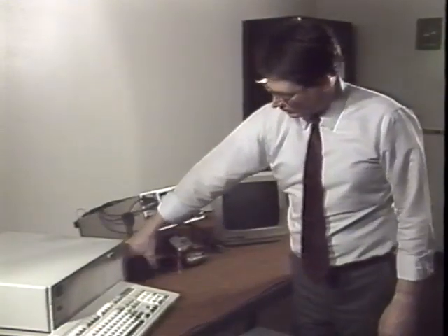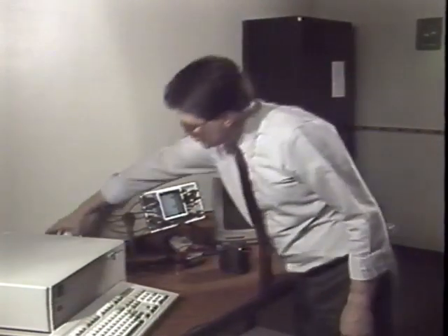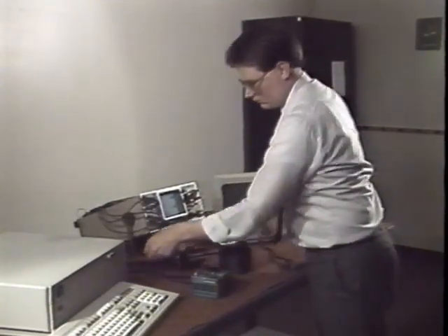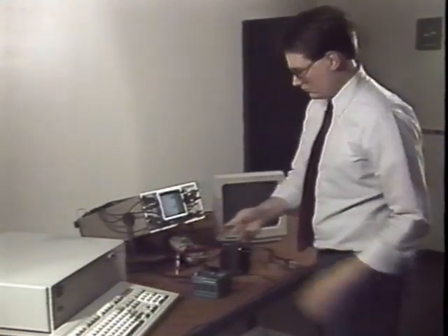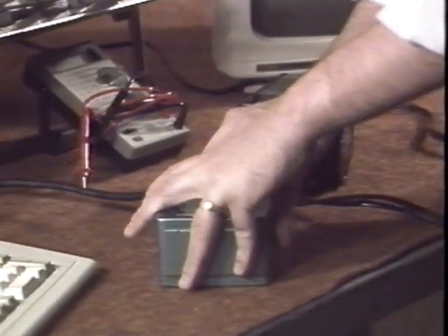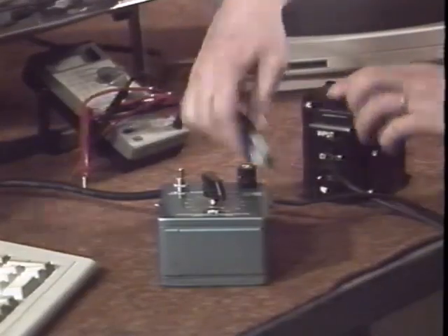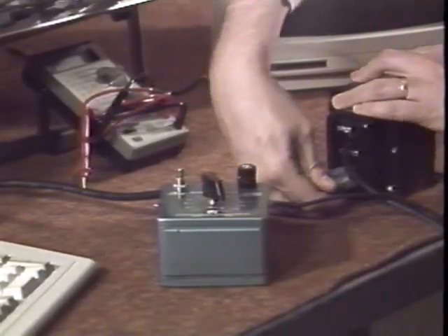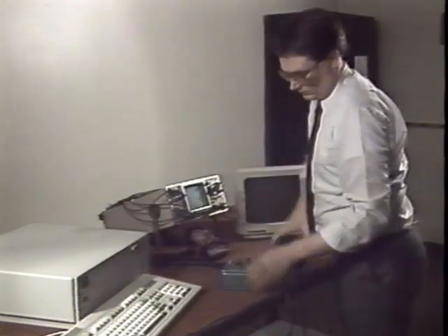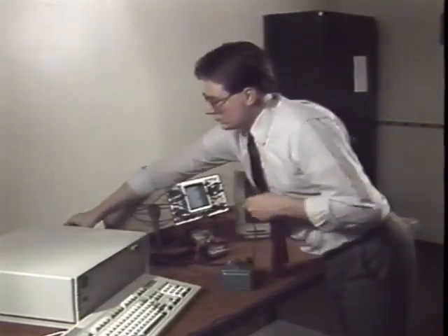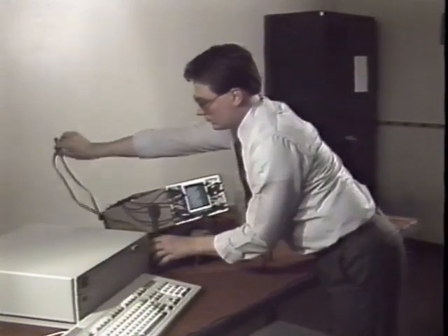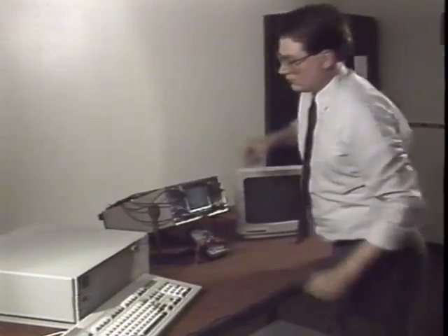Before completing our tour of the video monitor, we must discuss a few general service precautions. As with all computer equipment, connect the monitor to an isolation transformer before attempting to service the unit. This precludes the possibility of mismatched grounds and accompanying damage to the monitor, test equipment, and, most important, the technician. Remember, a variable transformer or variac does not provide isolation. Do not use a variac in place of an isolation transformer. If you need a variac, use both.